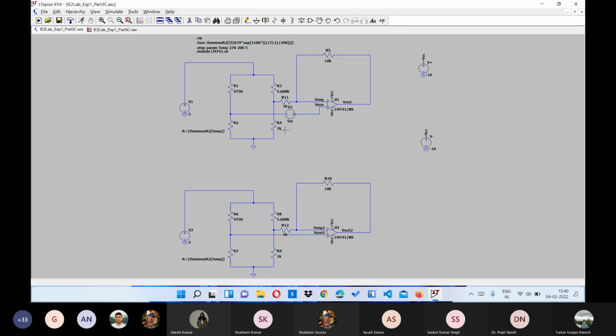The reason is the bridge constant. There is something called the bridge constant, which is dependent on the resistor values. So maybe visually you may not be able to see the difference. Why don't you do one thing? In the same graph, plot for one resistor pair value you have taken, R2 and R4, let's say 1K and something. Instead of 1K, whatever value you have taken, just make it 2 times or 4 times and see what happens.